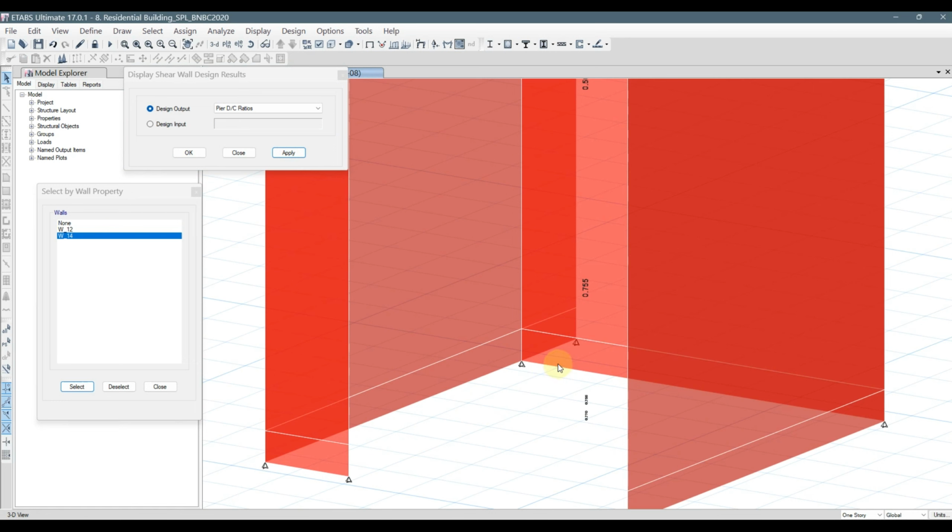So you see that when we used the uniform reinforcing at 4 inches spacing, 20 bar, we had 78% demand capacity ratio. Now we have 76% because more or less we have kept the reinforcement same. We have used some distribution reinforcement. However, we increased the amount of reinforcement at the edge. We used 20 at the rate of 3.5 inches spacing.